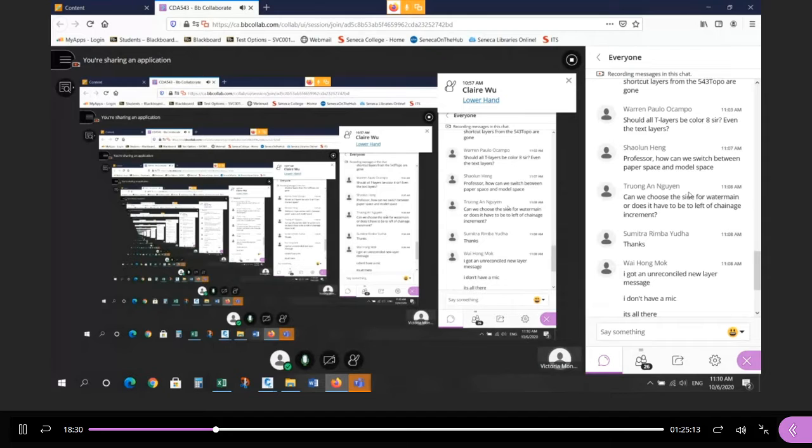I want you to see the service layers, right? Because they're going to be the sanitary, storm, and water. If you leave them in color, you'll at least be able to see that they're dashed. So the line type will take care of the fact that they're existing as opposed to the color, because we have solid lines for sanitary and storm.